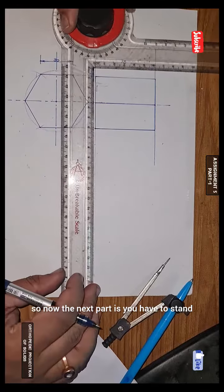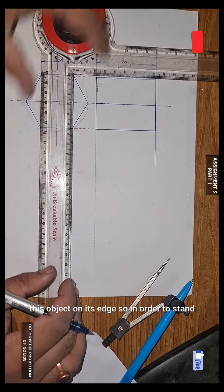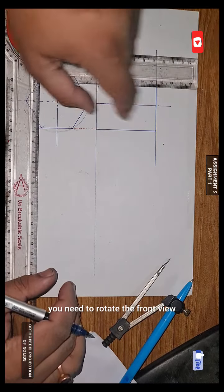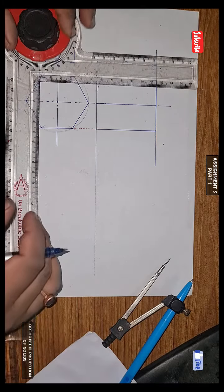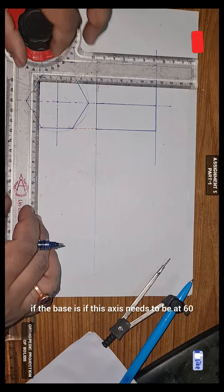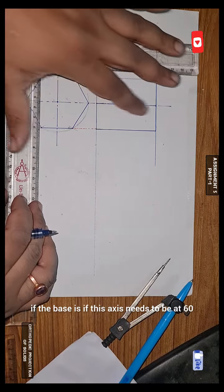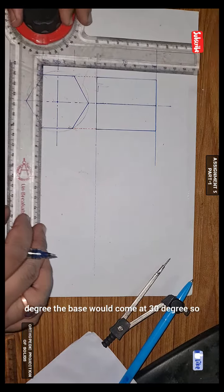So now the next part is you have to stand this object on its edge. In order to stand, you need to rotate the front view, because we are making the angle with the HP. So if this axis needs to be at 60 degrees, the base would come at 30 degrees.